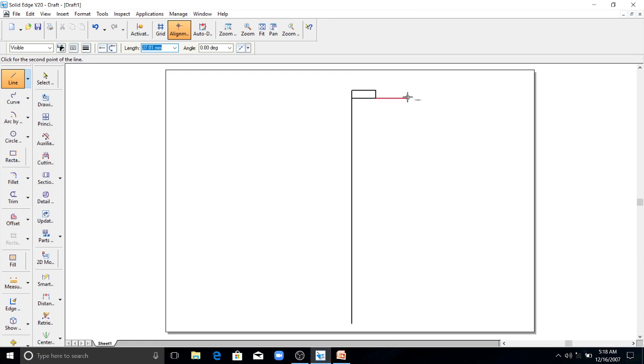You can draw any line and draw the section lines at the end, so that it shows it is a sectional part. This part has a particular length, that is 1.5 times the diameter. Now you have to draw a 10-degree taper line from here.